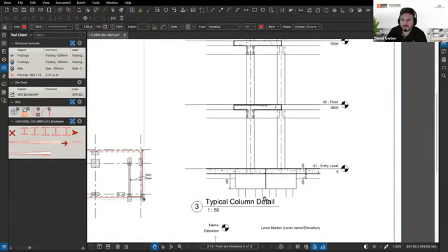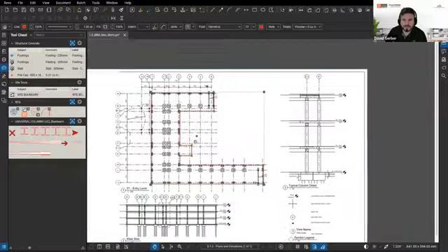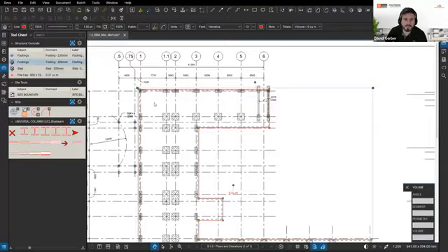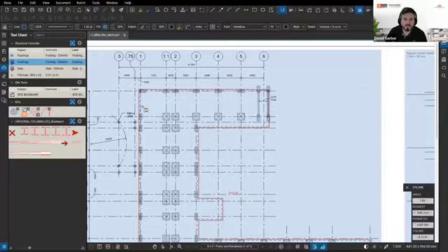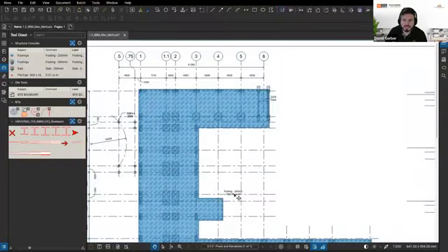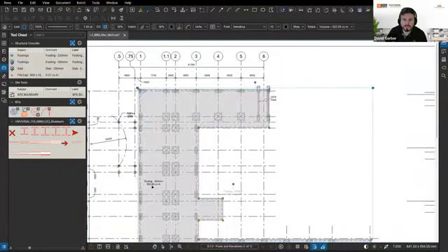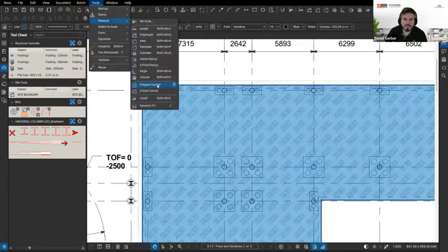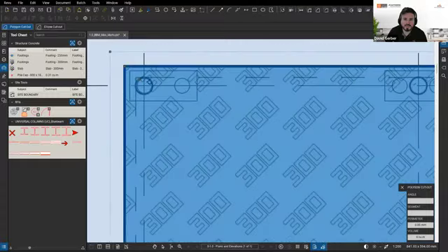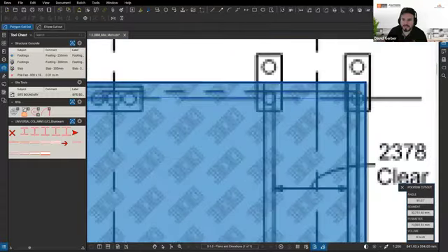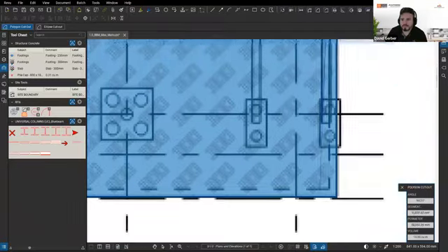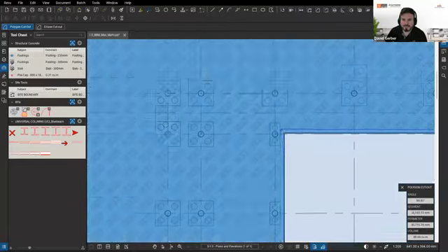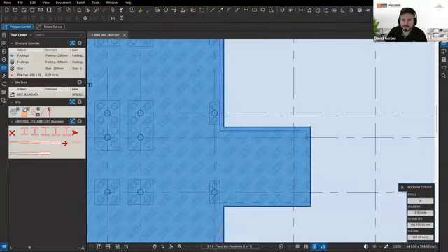So if I look here, my slab is 300 mils. So then I'm just going to use my 300 mil and just holding control, I can convert it. Again, you can see it brings in all the information from my markup, which is really nice. And then I'm just going to use the polygon cutout. So then I could just cut out where that slab is going to be. So just a little bit faster than drawing it and adding vertexes and stuff